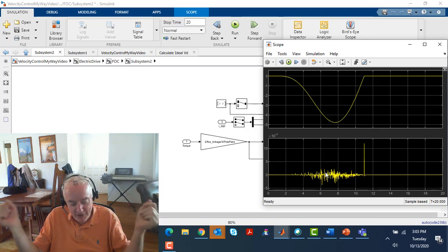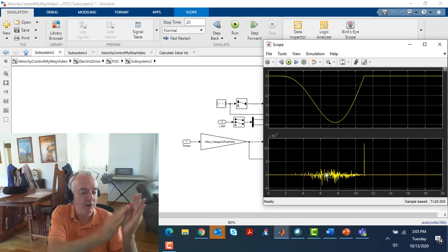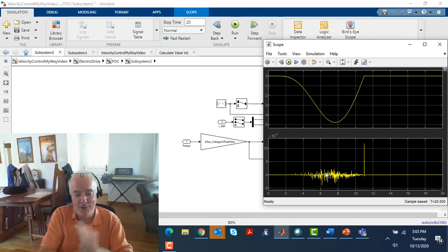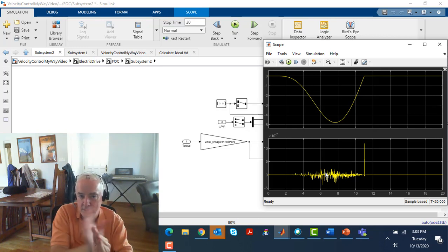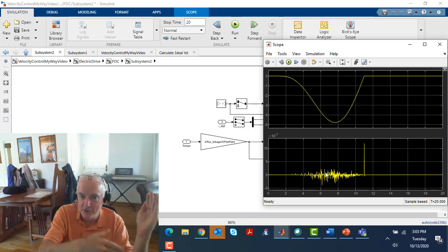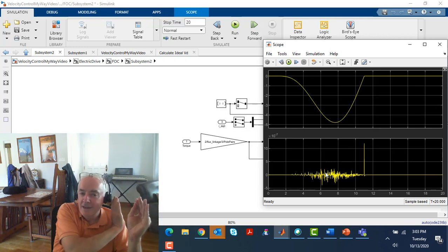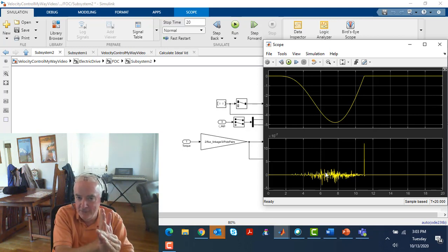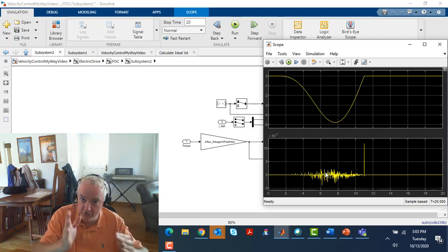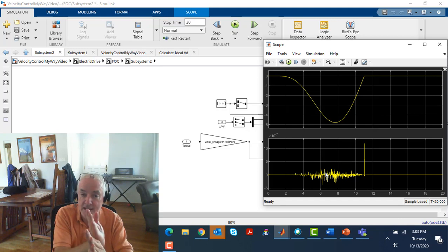And so here's another idea of what PIDs are like. I almost think of them as rubber bands, and if I were controlling with feed forward some lever that does something like this, it's almost like my conception of what this lever is that's operating on the controller. I can do my best to estimate it, but it's good to have something that sees a divergence between what I think it is and what it truly is, and that applies something that essentially has a restoring action to keep them moving together.